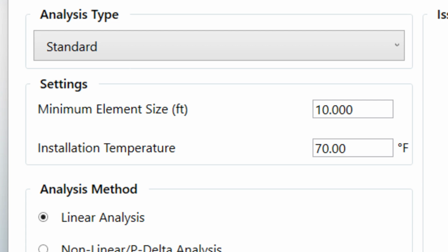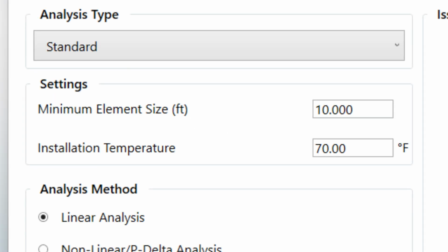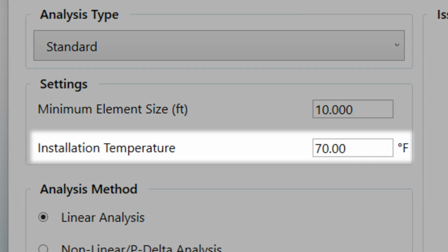If we do have guy wires present, then this entry becomes much more important. When the stack tries to thermally expand, that growth is restrained by the guy wires. It can represent a very large force on the guy wires, stack, and foundation. The temperature entered here represents the most likely ambient temperature that would occur when the maximum lateral load condition were to occur.